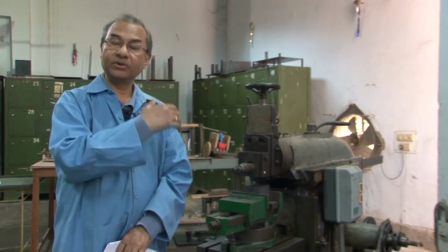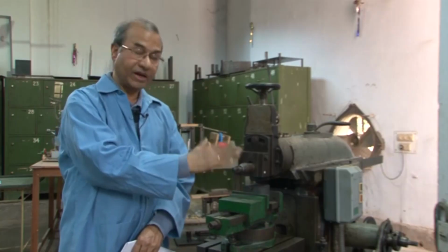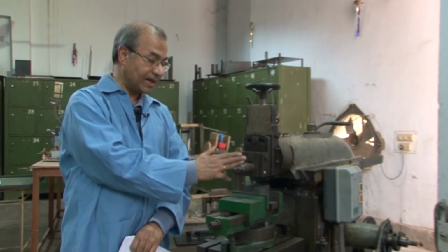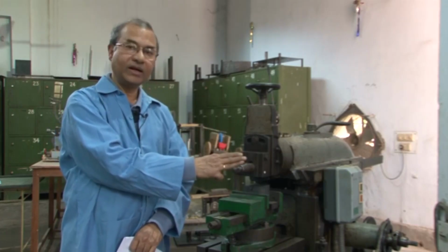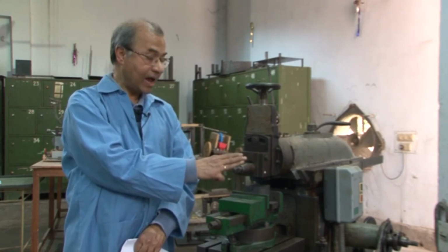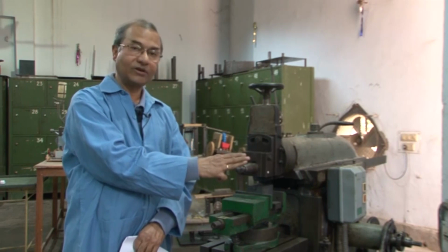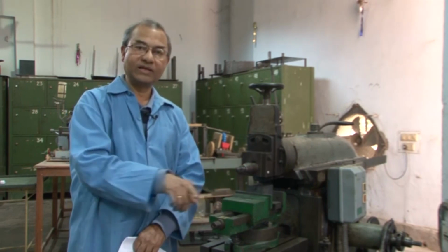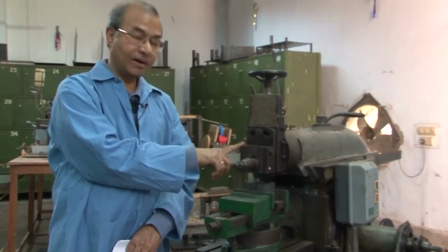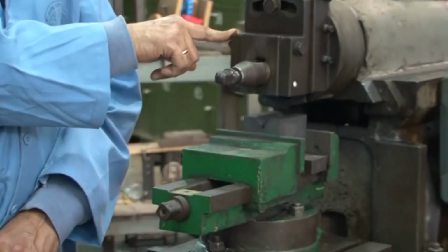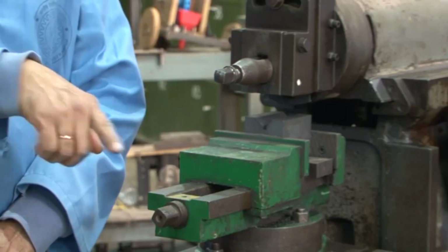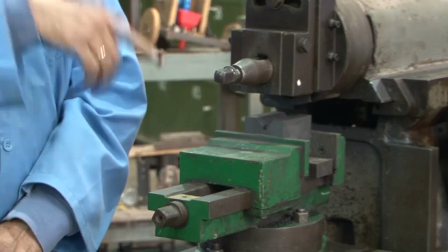We are not going to show you the planing mechanism, the planing lathe or planing machine, but in this example of the shaping machine it will be very clear how the planing can be operated. It is only that in case of planing the workpiece reciprocates instead of the tool as in case of shaping, and the feed movement is given to the tool in the same direction perpendicular to the motion of the workpiece.